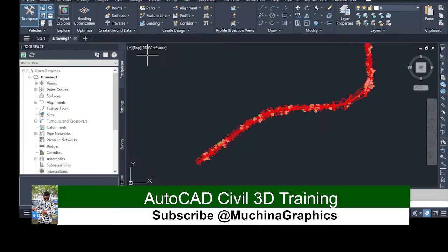So the thing that you need is to go to Home tab, and then you click Points, and then you click Point Creation Tool, and this Point Creation Tool will appear here, and then you click here Import Points. And then after that, you need to click this plus button, and you get to select your points where you have saved them. So in my case, since I have imported, I will not select anything, and then you get to change your file formatting, depending on the data that you have. So with that, I hope that we are together.